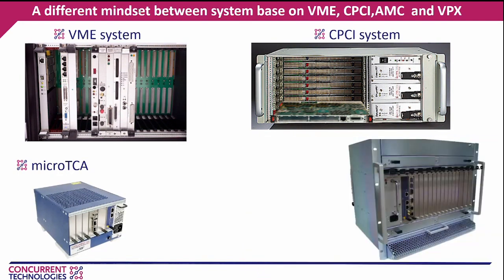So an example is micro TCA. Although micro TCA is point-to-point, it still is fairly easy to use because everything has been frozen and defined such that all the slots connect to a central switch called the MCH. And there is very limited I/O also defined with micro TCA.